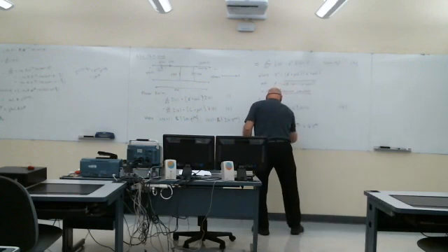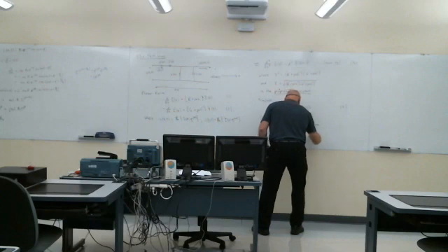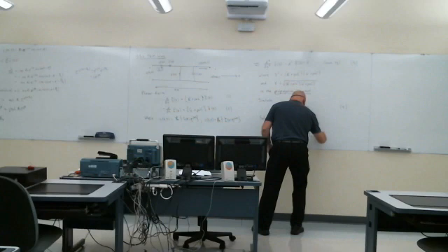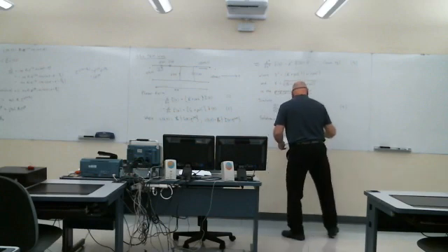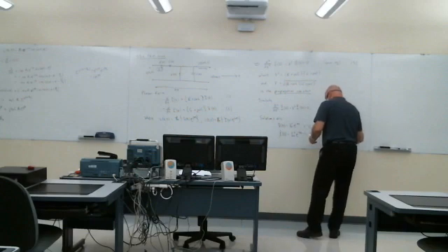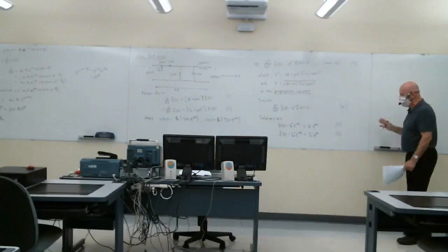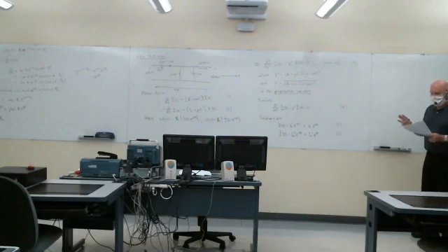And we have the same for our current phasor. We have a portion that's propagating down the line and a reflected portion. So we'll call these 5 and 6, where V0 plus, V0 minus, I0 plus, I0 minus are all complex constants.